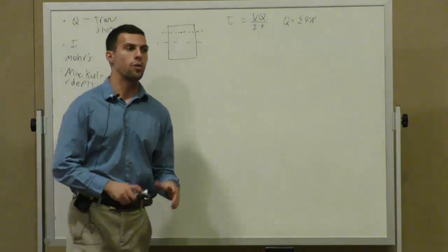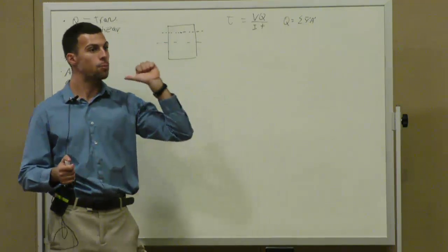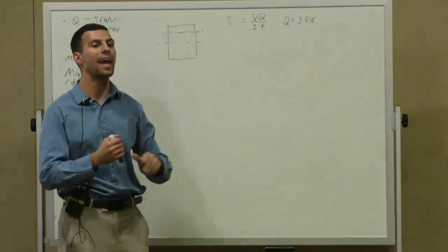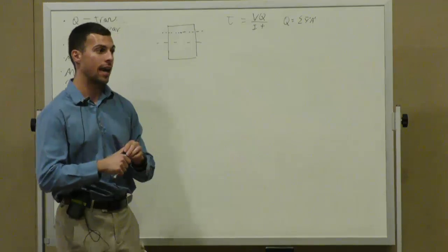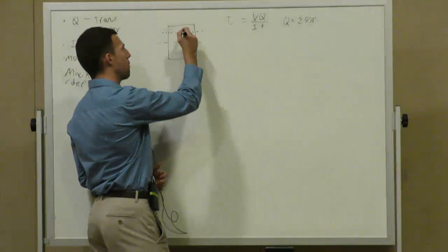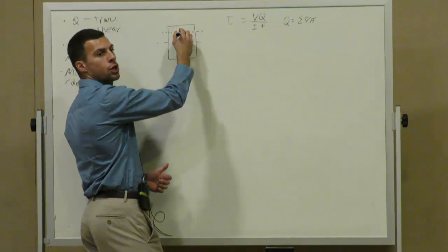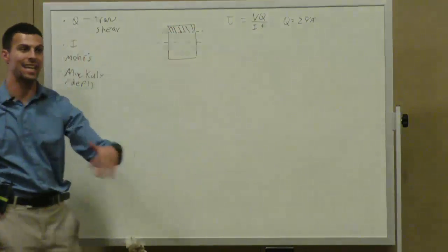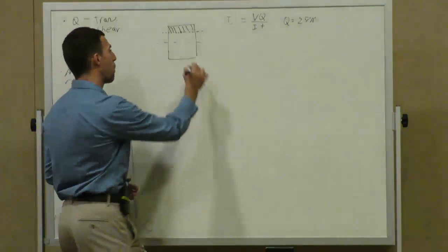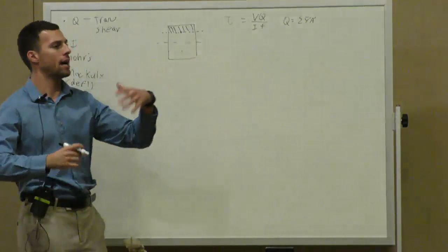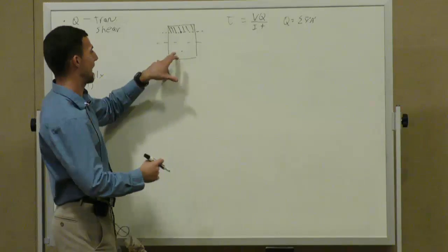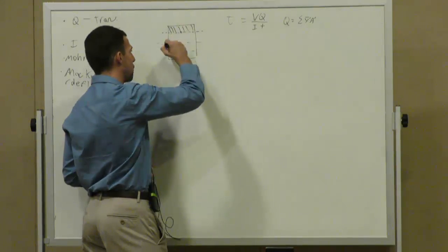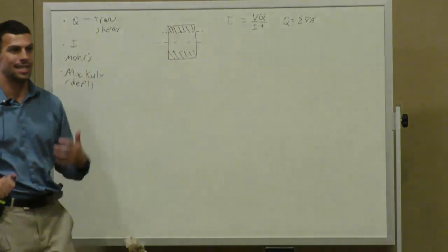Yes. So the area of interest starts at your point of interest and goes to the edge of your shape away from your neutral axis. What that means, go to your point. It is the area to the edge that is away from the neutral axis. The way I say it in that very confusing manner is because if your point is below, I don't want to say it's the area above it, because in this case, above would be wrong. It is the area to the edge away from the neutral axis. Does that make sense?